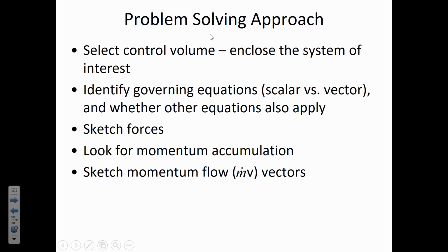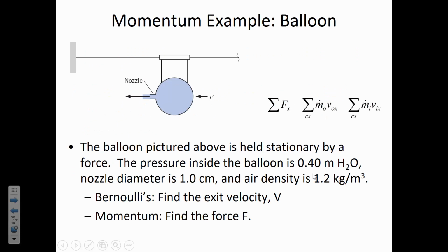The suggestion is also in the book that you try and sketch any external forces that are applied and pay special attention to the direction of the force that's being applied, if the force is to the left or to the right, and how that applies to our assumed directions for the convention. And then sketch the momentum flow vectors, just sketching the stream of water, the stream of air, the momentum flow being the system itself as it moves.